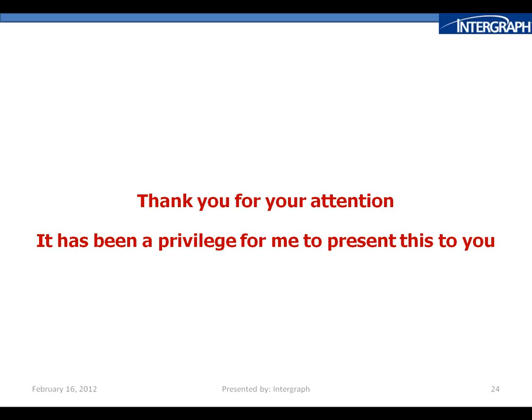Provided you adhere to all the rules of the ASME code, I presume you're talking about ASME, and the AI, the authorized inspector, will allow you to do this. You can certainly do this. My experience has mainly been in South Africa, where I was the authorized inspector, and I would regularly allow a person to increase the amount of radiography.